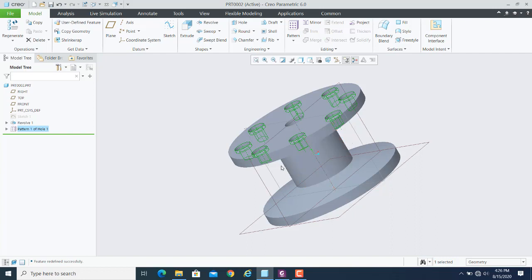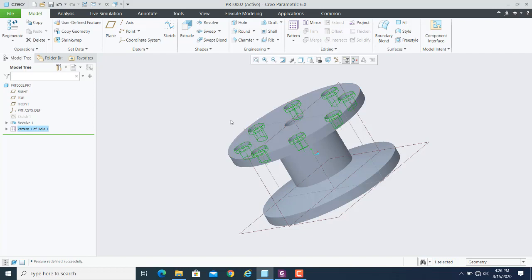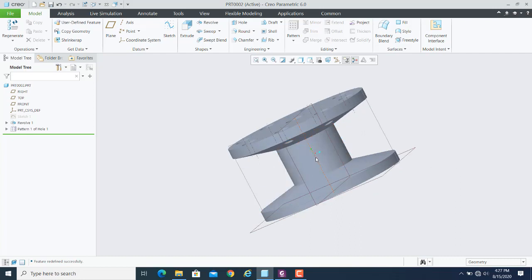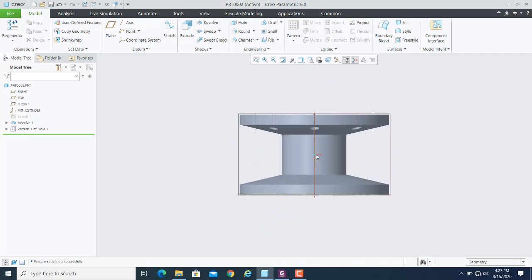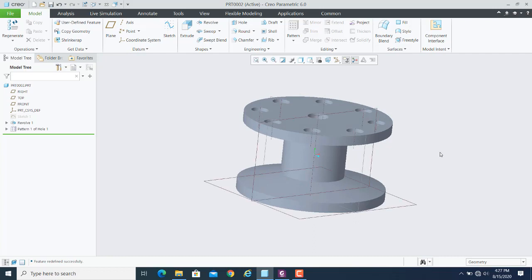But if you remember, in AutoCAD, if you want to mirror a feature, you also need a mirror plane. Okay, I will select this hole here, but what should be the reference for the mirror plane? It should be exactly at this midpoint. If I click on the front view, I must have some edge or a line or a plane which will exactly pass through the midsection of this circular region, so that I can mirror these features along that reference, which right now I have nothing. So what I can do is define my own sketching plane, a datum plane, which we already covered.